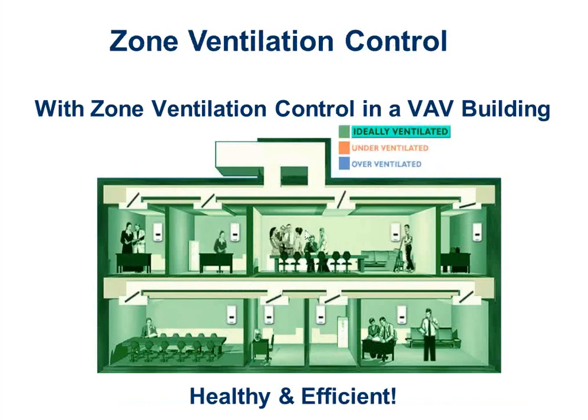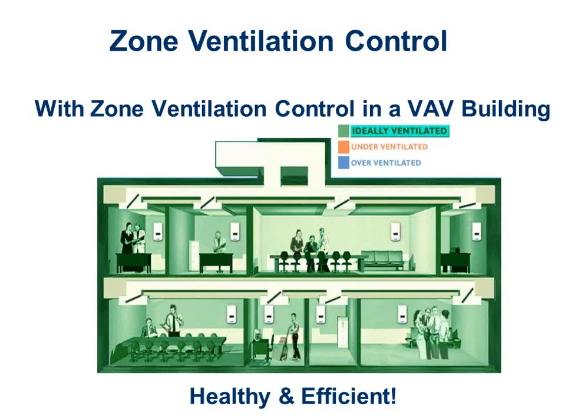So let's say everybody comes into this conference room right here in the middle. Everyone piles in right there. Right, so everybody just piled into that conference room. As they pile into that room, they're breathing. That breathing is recognized by the CO2 sensor, and that CO2 sensor tells that particular zone damper right there in the ceiling to open up more and to allow some more fresh air in.